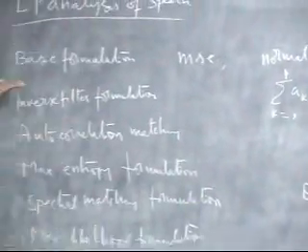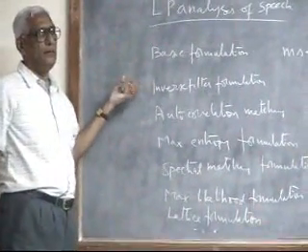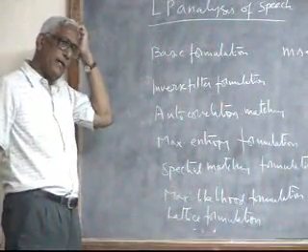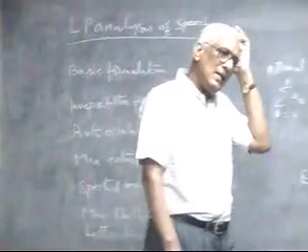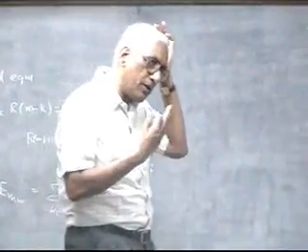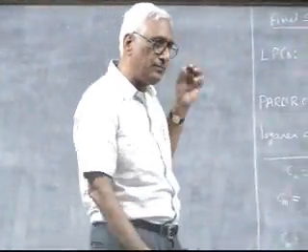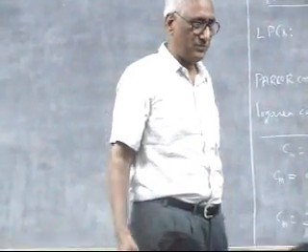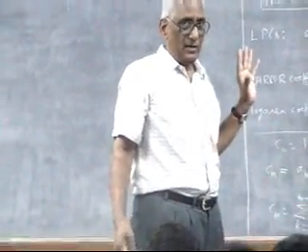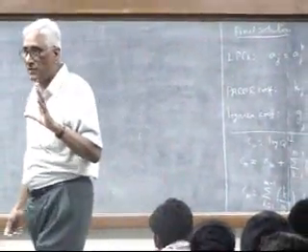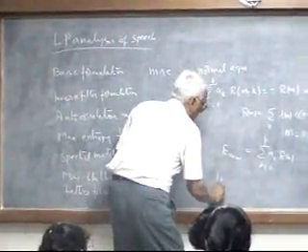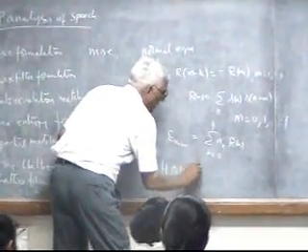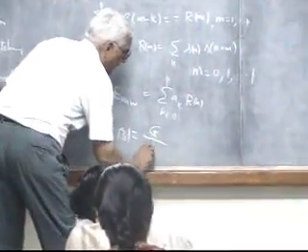And not only that, when we started interpreting it carefully, what we have noticed is that it results in modeling a source production mechanism, in this case speech, as an all pole system, that we have already done, where the model H(z) is given by G by A(z). You recall that H(z), the all pole model for this, is simply given by G by A(z).